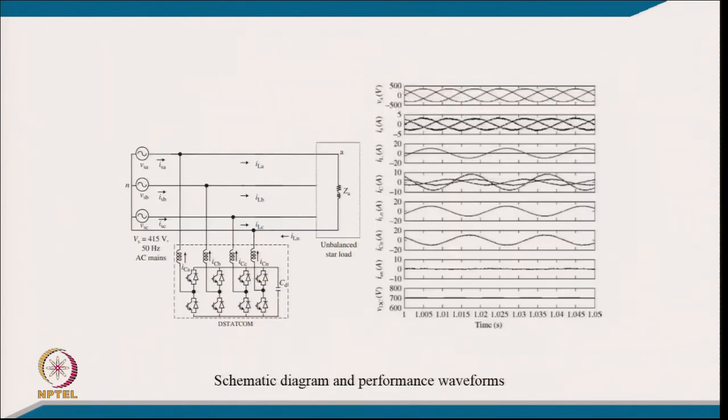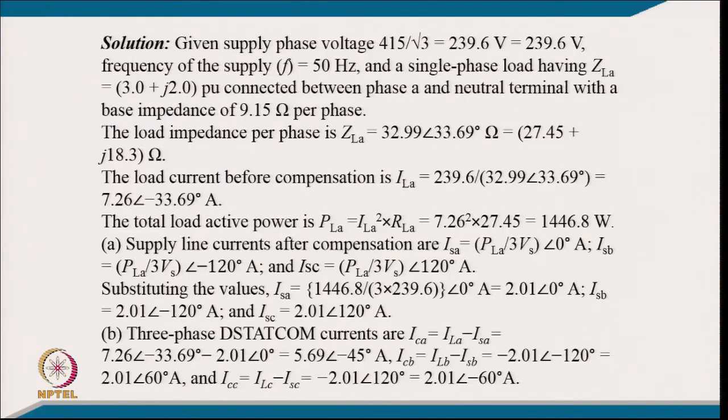So, these are typically 4 leg compensators we are using, and the load is connected between one phase and line, a lagging power factor load. So, the very purpose of the DSTATCOM is to provide, let us say, neutral current 0 and all 3 currents equal, balanced and at unity power factor. So, after designing and with the power control, you can find the 3-phase voltage, 3-phase balanced current at unity power factor, then you have a load current, then you have a compensator current, and load neutral current and compensator neutral current, and you can see your source neutral current is made 0 because the load neutral current is compensated by the 4th leg of the voltage source converter, and the DC link voltage is regulated to 700 volt according to the design.